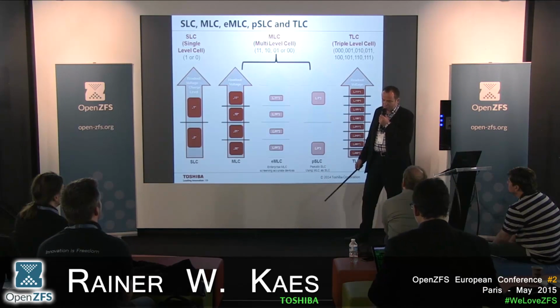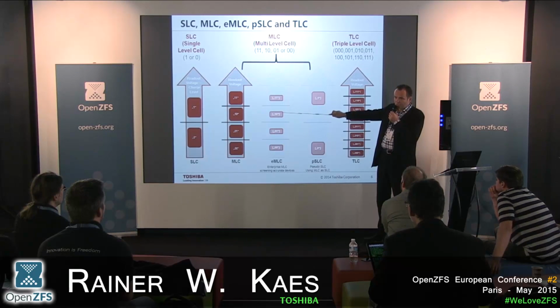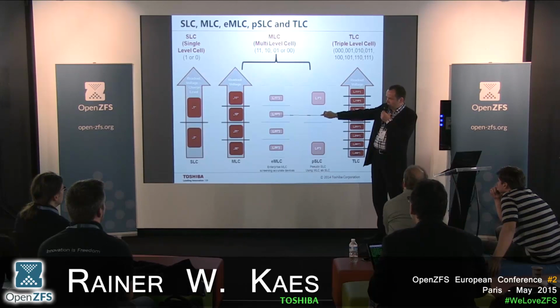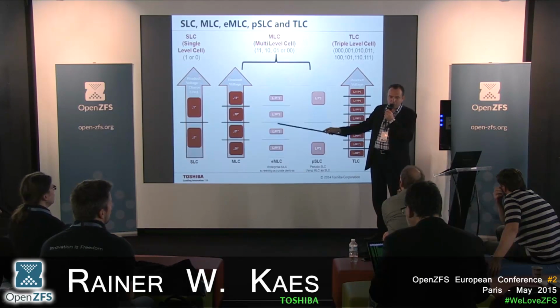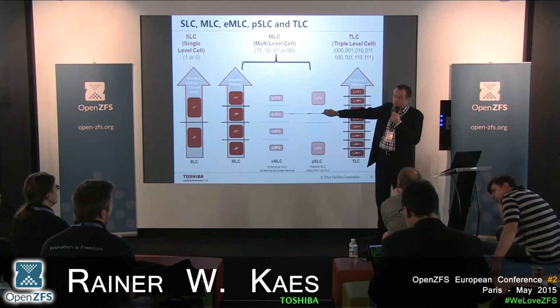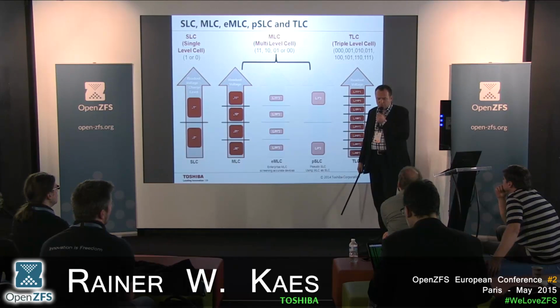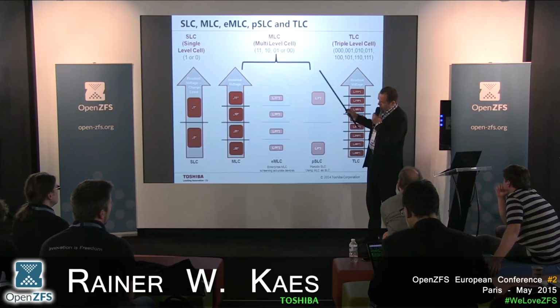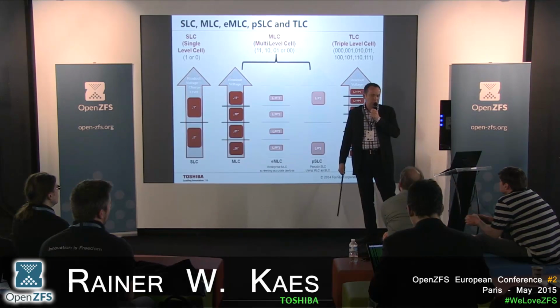And what it effectively brings is devices where, if we want to write 66%, we write not here and not there, because if we write there, we can tolerate less damage before going to the wrong value, but we use only the ones where, if we write 66, we are exactly at 66. And this gives us higher margin, more erase cycles tolerated until we are leaking out to the wrong value. So it's just a selection process that selects the good devices where we are sure we are writing into the center. The yield of this selection obviously fluctuates, but with good quality control and good process control, many times more than half, if not 80%, can be used at enterprise MLC quality.